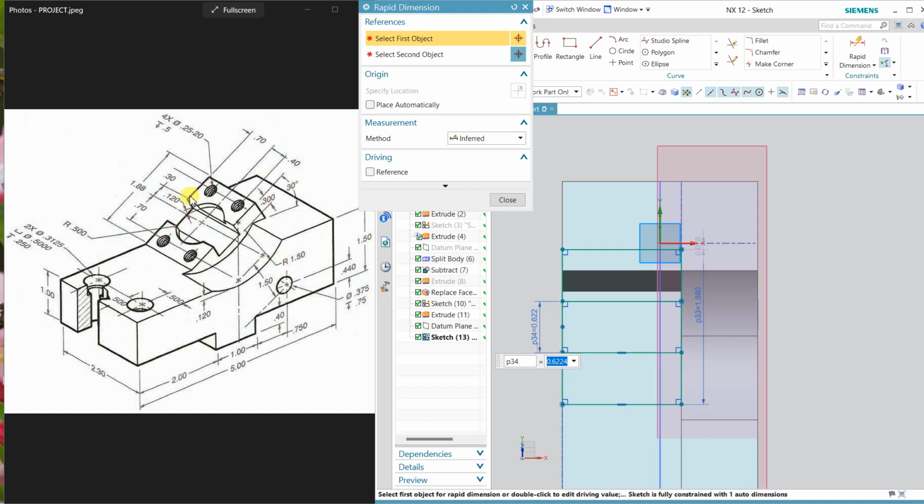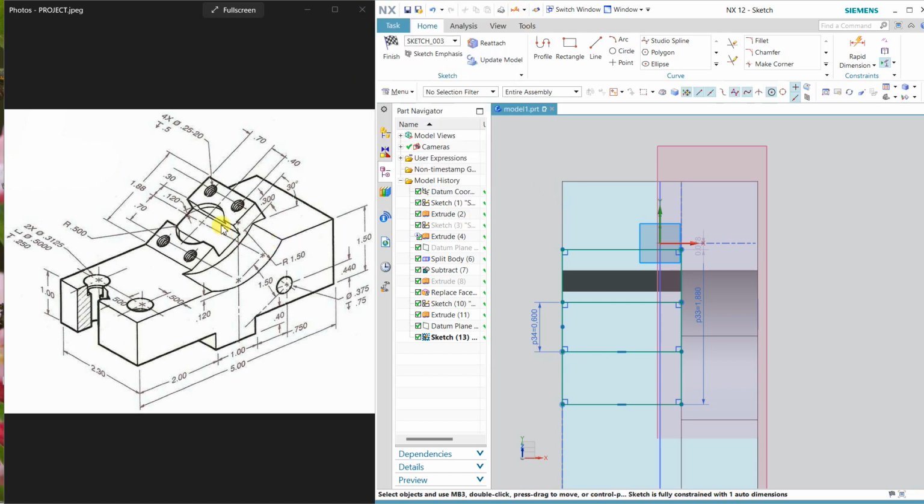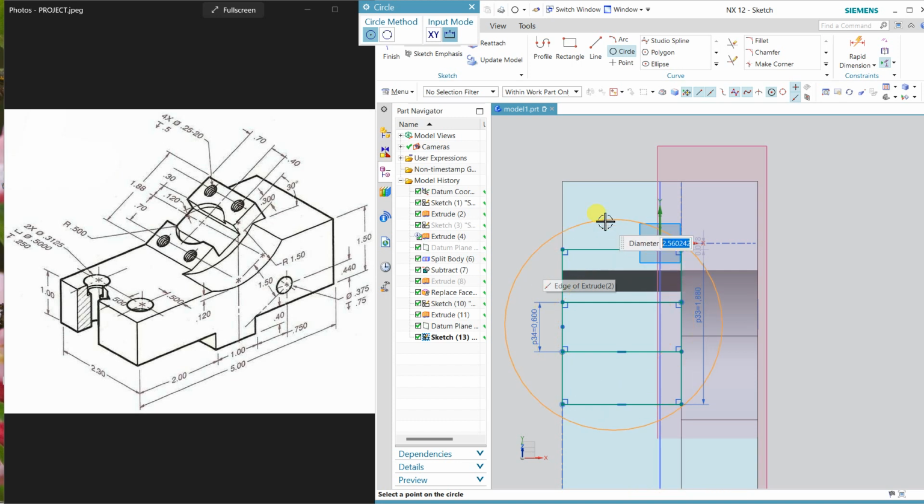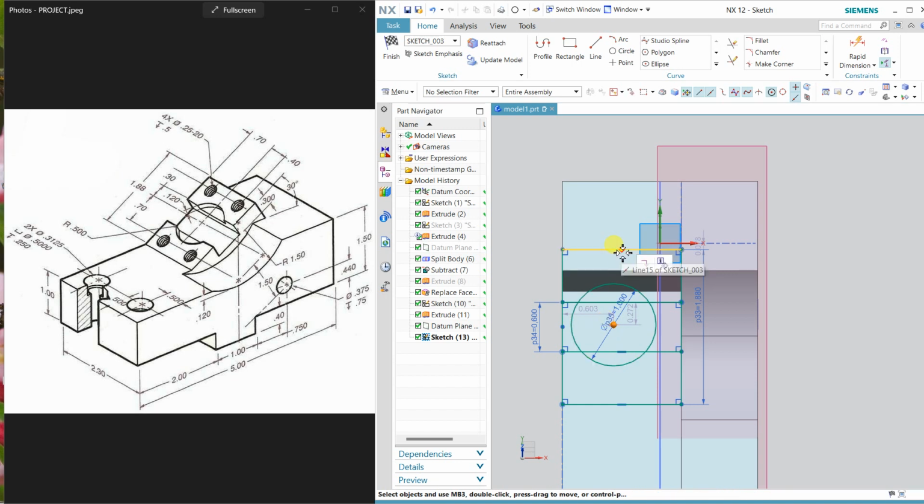Select this, and see this gap here. So we have to find this gap, 0.3 from the center and 0.7 from here. This is 0.3, so double of 0.3 is 0.6, and click OK. And one circle is there, so the circle is 0.5 radius. Click and draw a circle, and 0.5 radius means 1 is the diameter. Now select the center and align with the vertical point, and this point will be matched from the horizontal alignment. So all the positions are done.